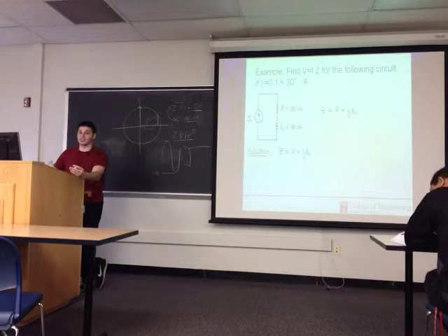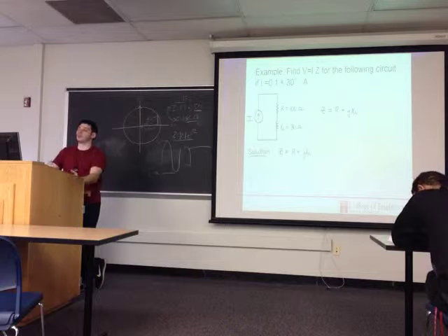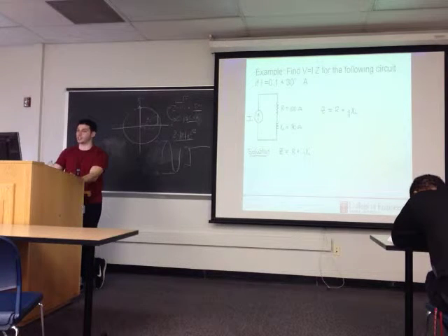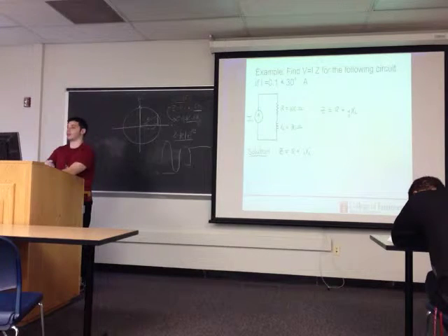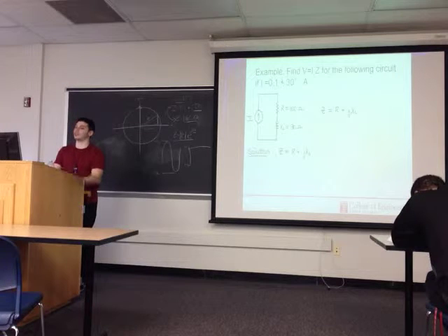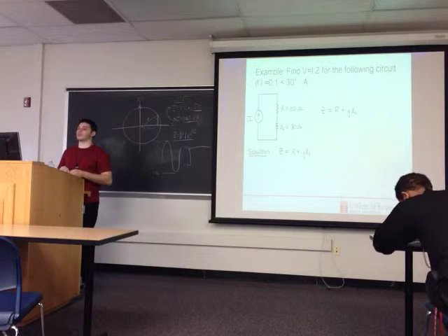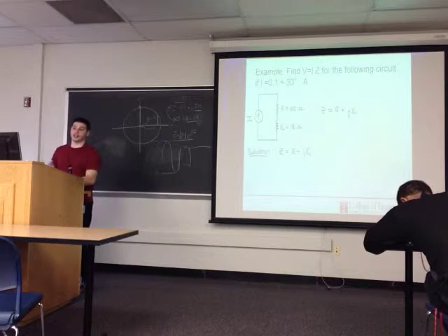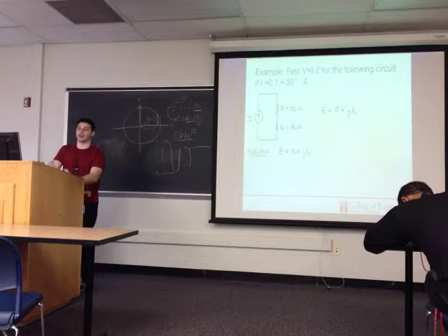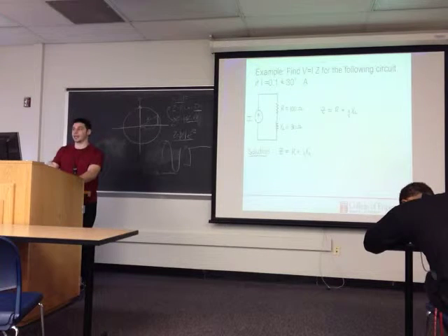Remember that impedance is a complex number. Complex numbers contain a real part and an imaginary part, two completely separate. The impedance of an inductor is just the imaginary part. The impedance of a resistor is the real component. The impedance of the inductor is imaginary, and it's represented by that formula a couple slides back, which is j omega L. Is that related to the fact that there's 10 volts and negative 10 volts for alternating current?